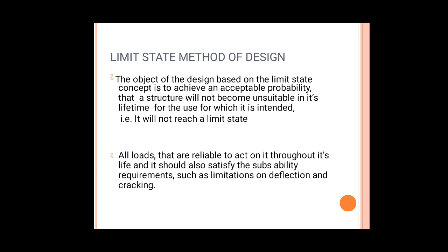The limit state method comprises two main points: the limit state of collapse and the limit state of serviceability. Further, it must consider all loads that are reliably expected to act, including dead loads and live loads through its life, and it should also satisfy serviceability requirements such as limitations on deflection and cracking.